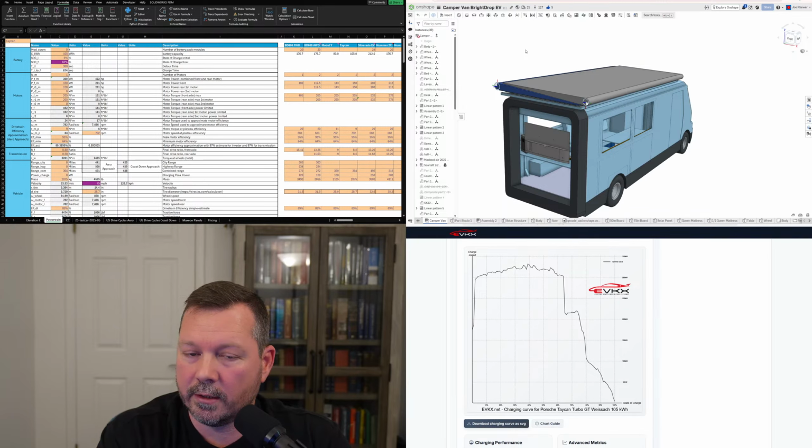sheet metal, something that could be laser cut really quick, laser cut bent, or maybe standard extruded aluminum. But I want to keep it economical to make, but at the same time, some of that extruded aluminum can get pretty expensive. So if you're doing any kind of volume, it's actually cheaper to just buy sheet aluminum, have it laser cut real quick, and then assemble it or weld it together. And you can get more rigid if you fully box in sheet metal.